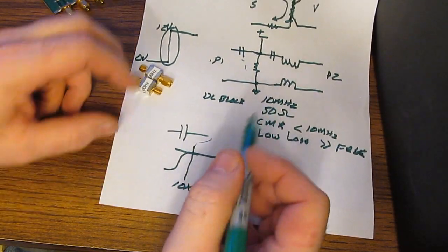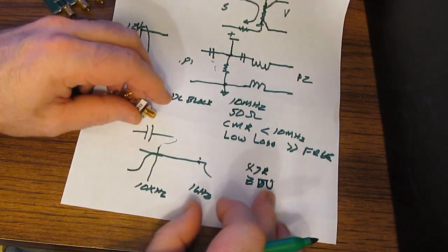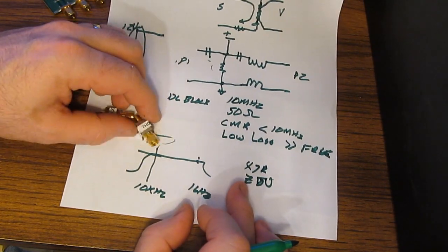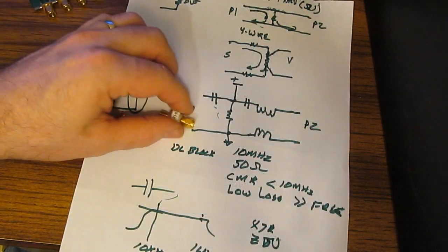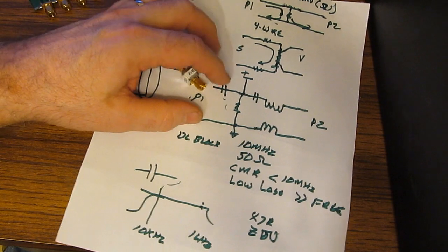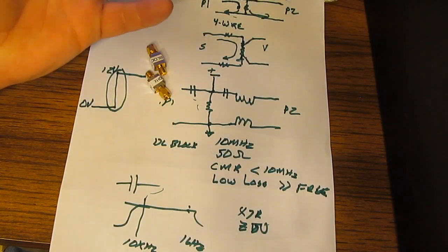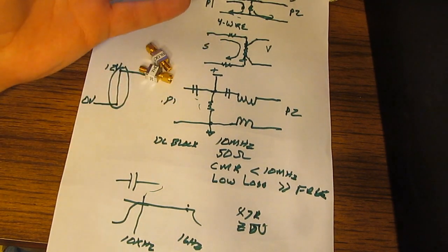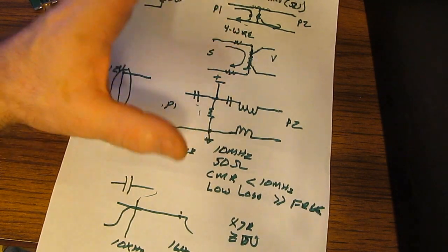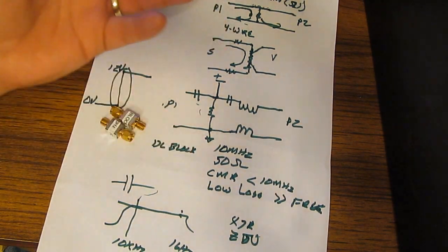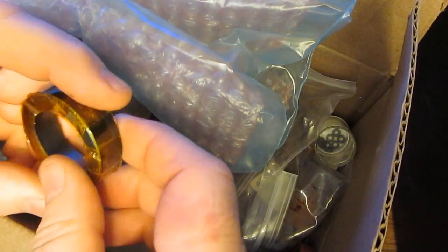Another thing that you want to be aware of is if you're using something like an X7R or Z5U, for example, the capacitance is going to be very unstable with the voltage that we apply across them. So again, just keeping in mind that that capacitance can change with the voltage across it. You have the same problem with the PDN itself, right? You've got a bunch of bypass capacitors. A lot of those are ceramic, and when you power up the PDN, the impedance is going to change versus having it off.